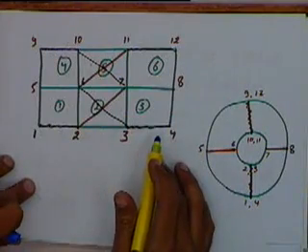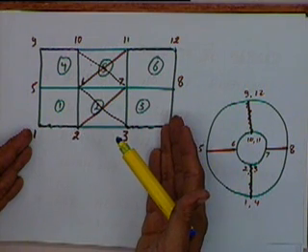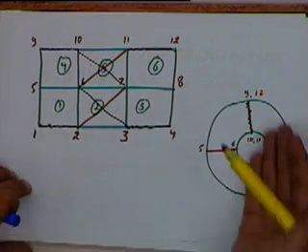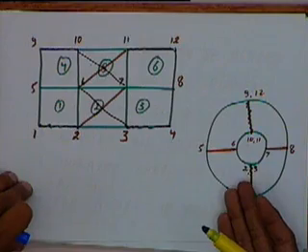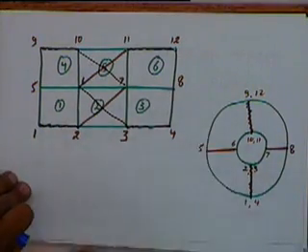That has to be done at a stage when we are trying to generate this shape from a rectangular array. The basic thing is we are starting with a rectangular array, and we want to map this onto any arbitrary shape. That operation requires some conceptual mapping, which has to be done by the person who is generating the mesh. It is not being done in an algorithmic manner.